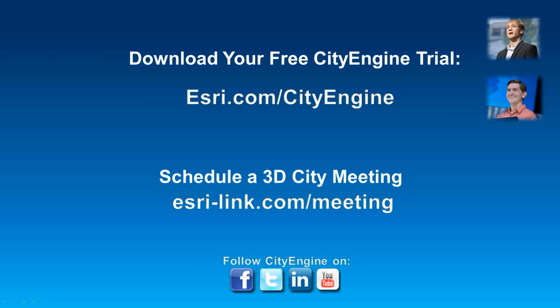So another one regarding cities in general. Can we see underground utilities in CityEngine? And yes, you can see them. The key with utilities is you want to use ArcGIS 10.2 or 11 when it's released and run inside of ArcScene operations to take the 2D data and turn it into 3D, just because we can't model pipes inside of CityEngine. You can then export those as a geodatabase format or a collada model into CityEngine and view those with the buildings, or you can take your buildings from CityEngine into ArcScene and visualize the pipes in relation to those and those utility lines to the city.